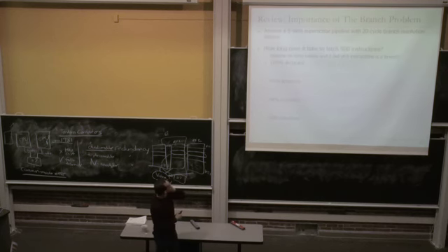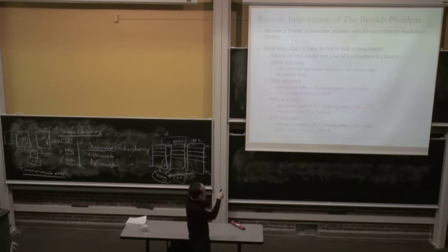Okay, so this is just to motivate you a little bit. We've seen that even with 95% branch prediction accuracy, with a deep pipeline, 20 cycle branch resolution latency, and fetching 5 instructions per cycle in a superscalar machine, remember superscalar machines do multiple instruction fetch at the same time, basically you're fetching 100% extra instructions.